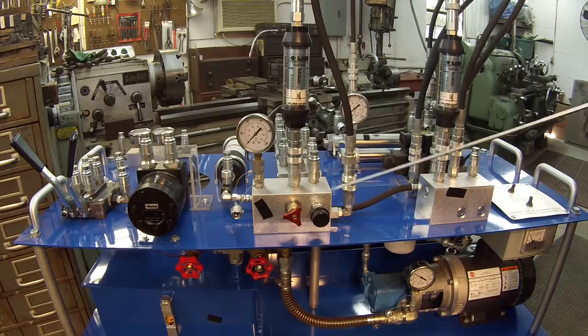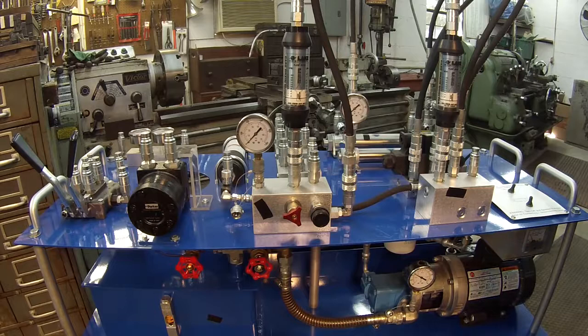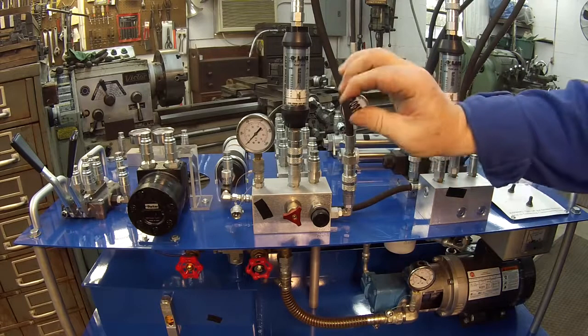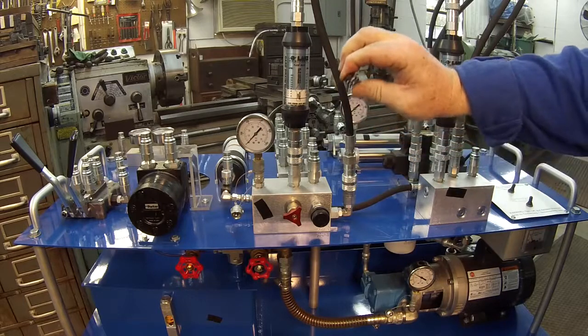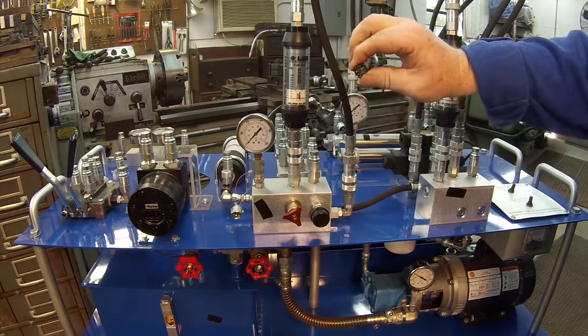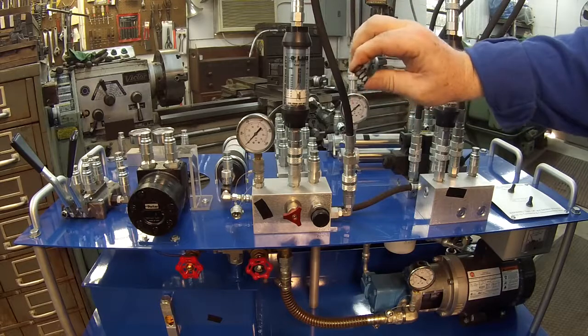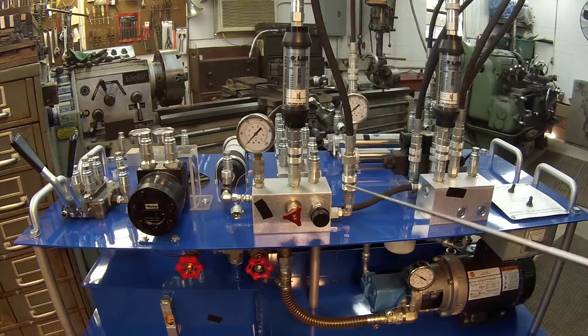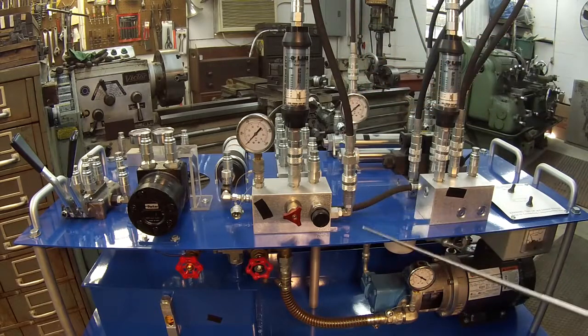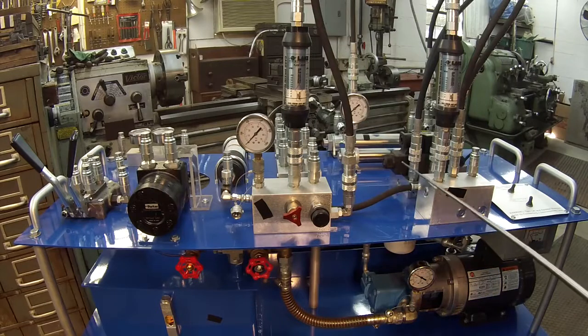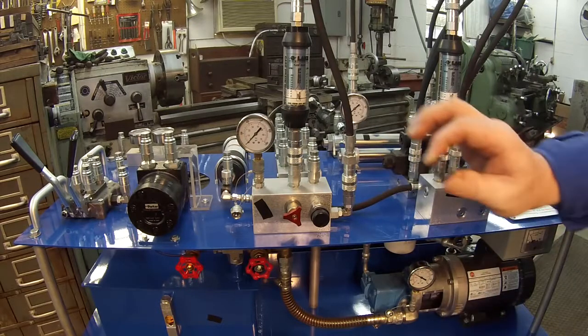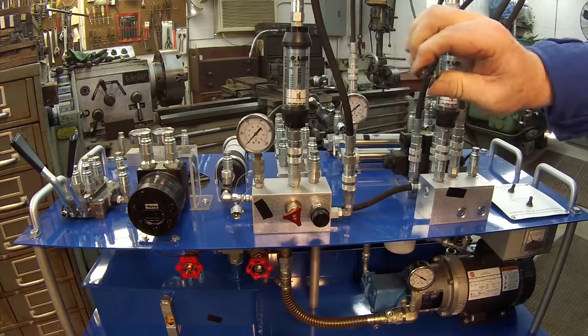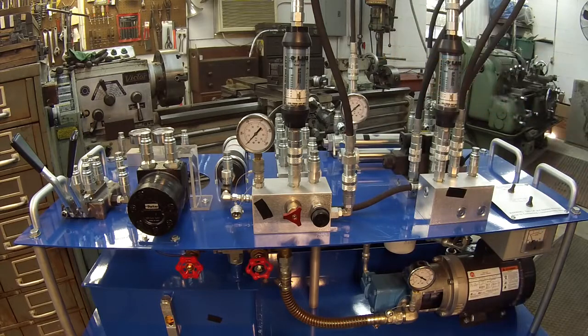The next one is any mechanical device. You have springs inside these mechanical devices like your relief valve that go back and forth every day. So with that mechanical motion over some period of time, that is going to break. A relief valve over a period of time, as it opens and closes, and on your directional valve here, as it moves back and forth, those springs over a period of time are going to break. So just expect that.